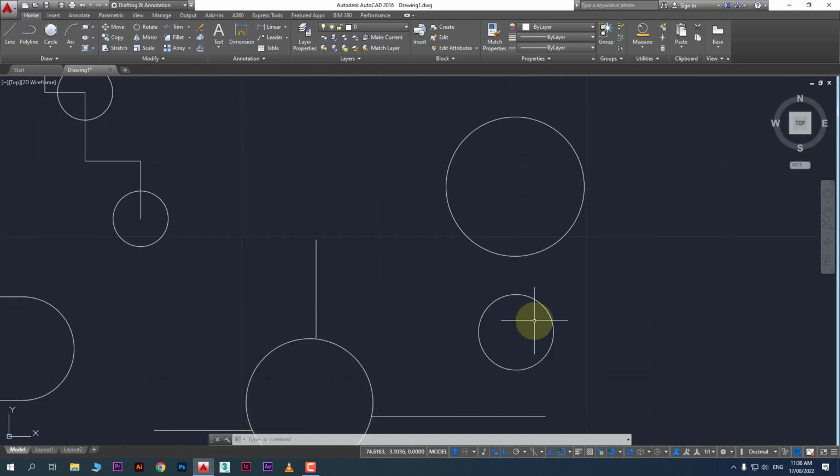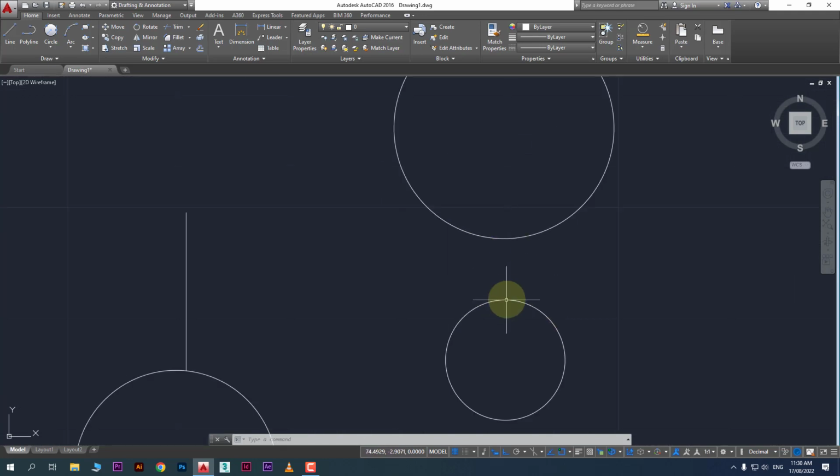So there can be two reasons. Either the distance between these two surfaces is greater than 0.1. If you want to check, go here, then Distance, and check from here to here. It's 0.2. We gave 0.1, so our circle was too small, so it cannot touch the surfaces of these two. So you also have to check the distance.